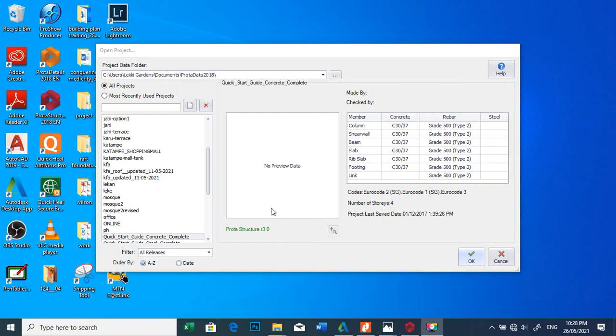If the soil at the surface is not too good, you need piles to take it down to where you have a firm soil. Or if you are building a high rise that has very large loads coming on the foundation, you will need piles to take care of that. So pay attention to those two. If your soil bearing capacity is not good at the surface, and when you drill down you get a firmer soil below, you take your piles to that.